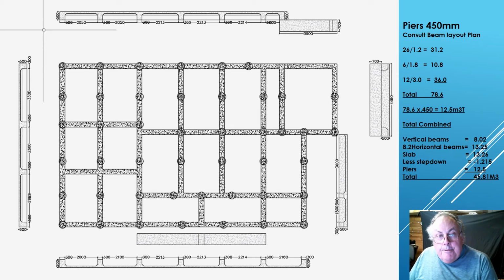The reason we've got beams here is because this slab is actually being built over the site of where there was formerly a dam. And so we would actually have something like this on your plan coming down, where this area is regarded as unstable. And so we need piers to actually go down.